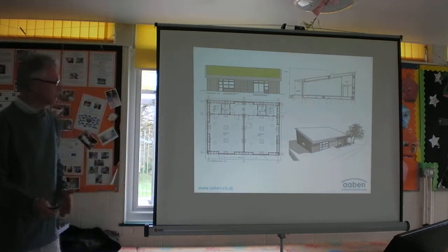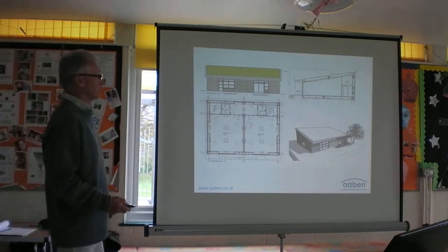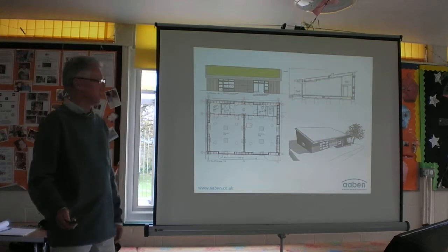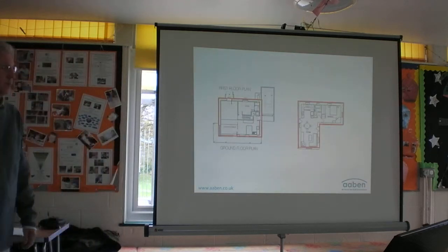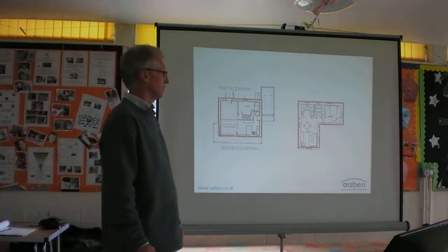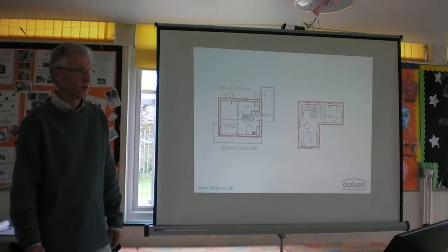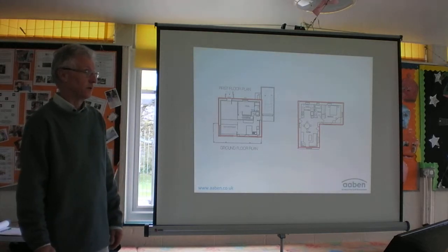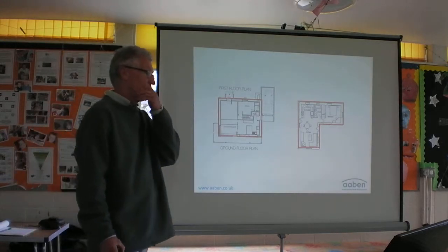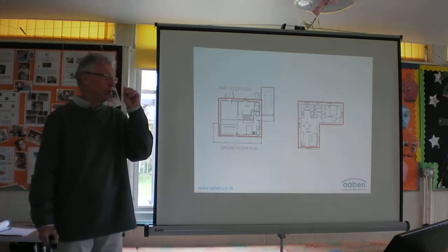Yeah? Ceiling heights are really important in that. If you're wanting to use nighttime cooling to cool the fabric of the building down, you need 2.7 metre high ceilings and exposed. You don't need it, but it makes a big difference. Can you not run the air in the foundations? You could, you could run the air anywhere you like, but then you have to pump it, whereas if you use passive ventilation, i.e. open windows, you can combine.